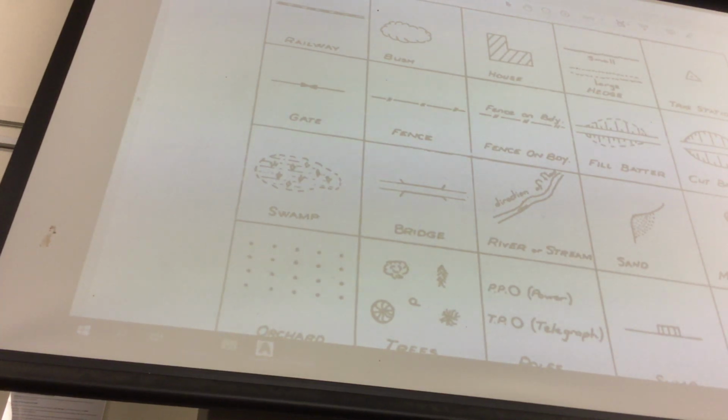Now let's just say that the wetlands or the river or whatever, the creek, is open at each end. You might be able to draw a line from there to there and then hatch it, but the chances are you're probably going to have to go around it drawing a P line.